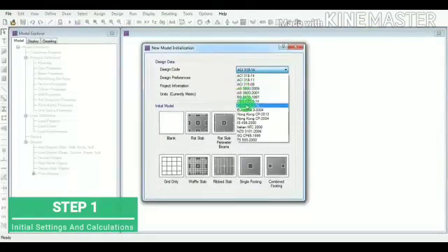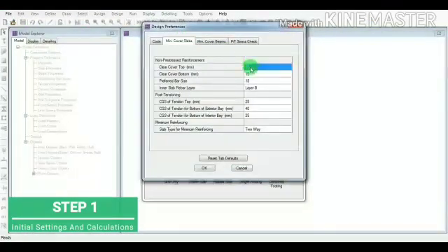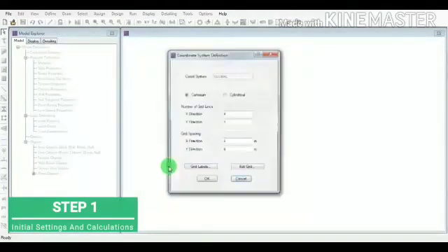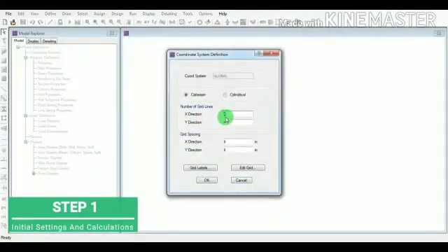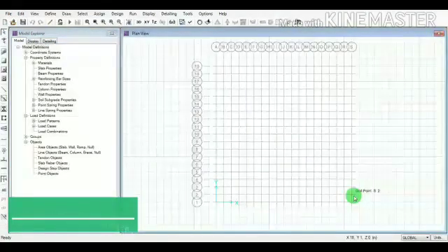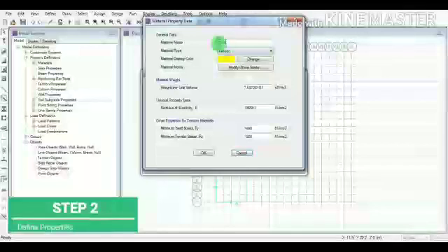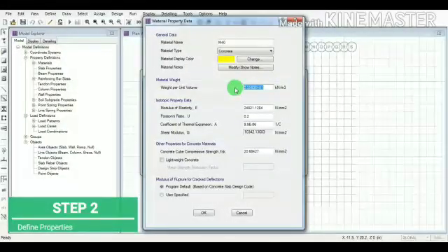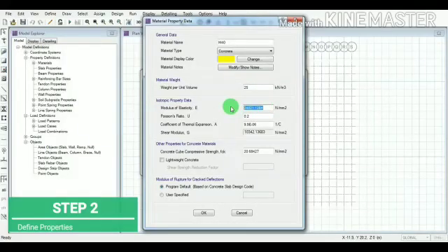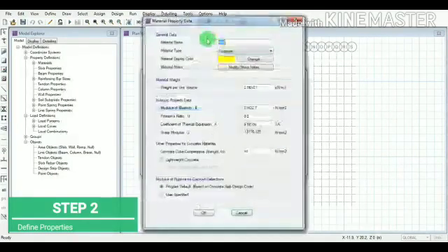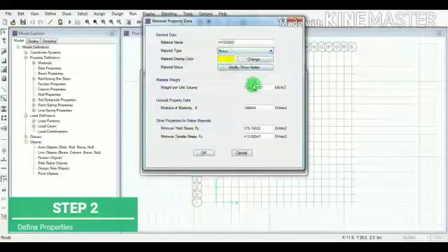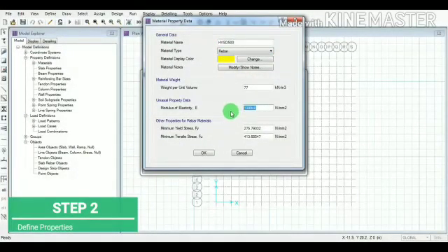Now go to the SAFE software and set IS 456. Then add the cover and rebar options. Then set the grids. The footing is 18 meters, so the grid lines will be 19 in both directions. Now set 1 meter. This is how we got the grid. Then go to the material, define material M40 concrete and add all the standard values for M40. Click on OK. Then add an HYSD 500 bar and add its standard properties.